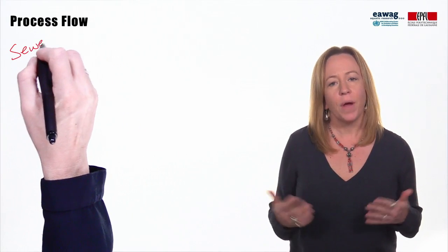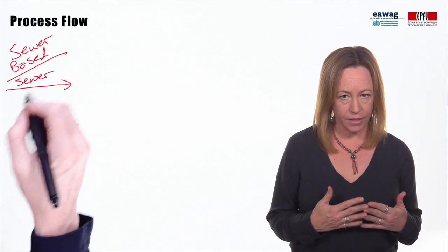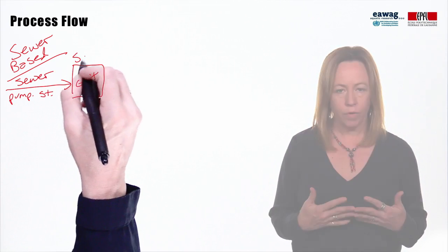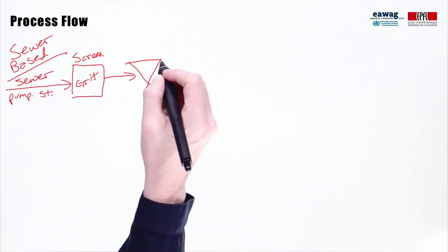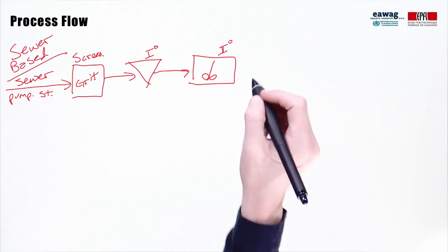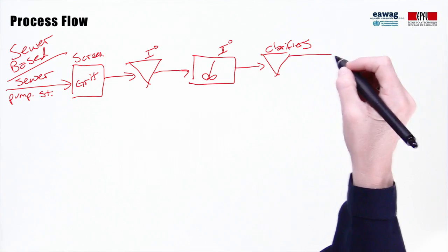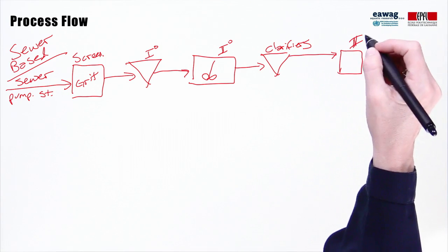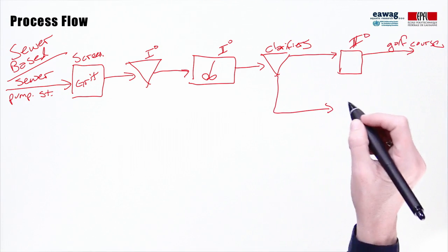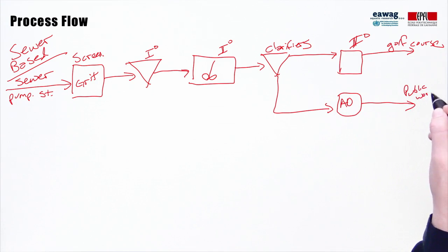First, let's compare both of the process flows. For the sewer-based system, there are sewer lines and pumping stations, followed by a wastewater treatment plant. The process flow has screening and grit removal, primary settling, activated sludge, clarifiers, with the effluent going to tertiary treatment with some water reclamation at a neighboring golf course and the remainder discharged to ocean. The solids go to anaerobic digestion with some of the remaining solids sold to public works for use in greenways.